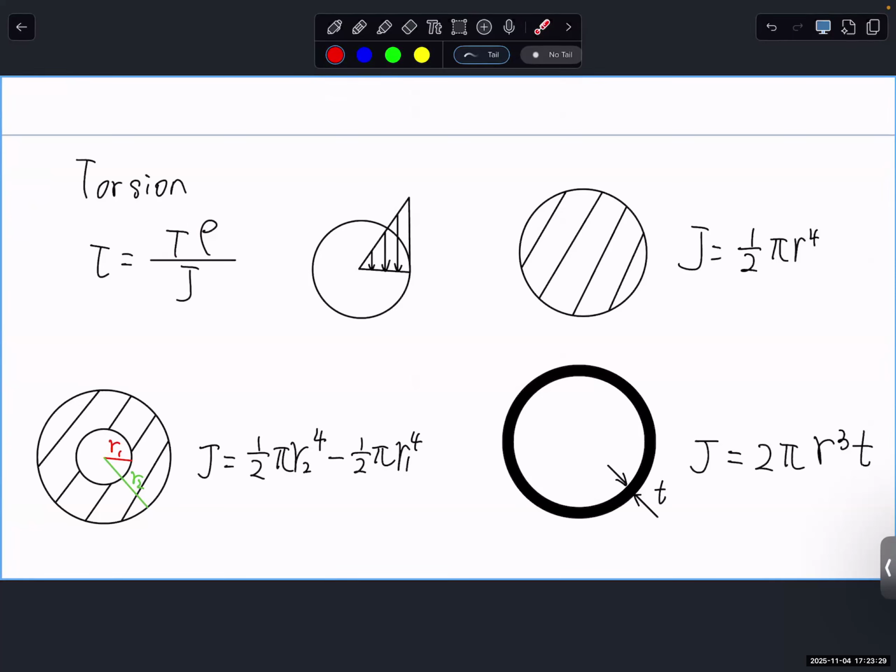So you want a thin wall so that you can resist the torsion? The thin wall is more like an optimization of a structure. Because from this equation, you can see that at the center of the circle, if it's solid, the stress is zero. So put material there or not, it doesn't matter because it does not carry any stress. And now if you move away from the center of the circle, let's move in this direction, the stress gradually increases, and the maximum is on the outer surface.